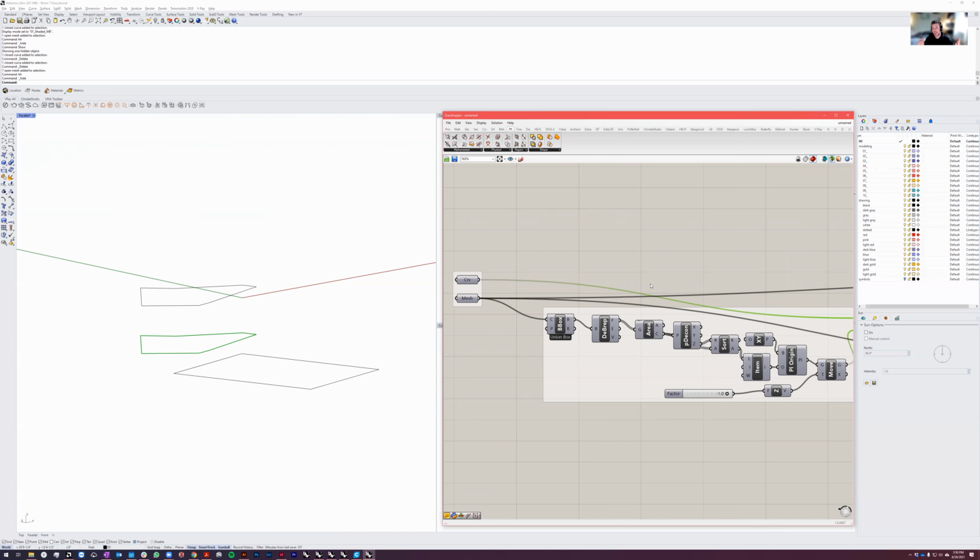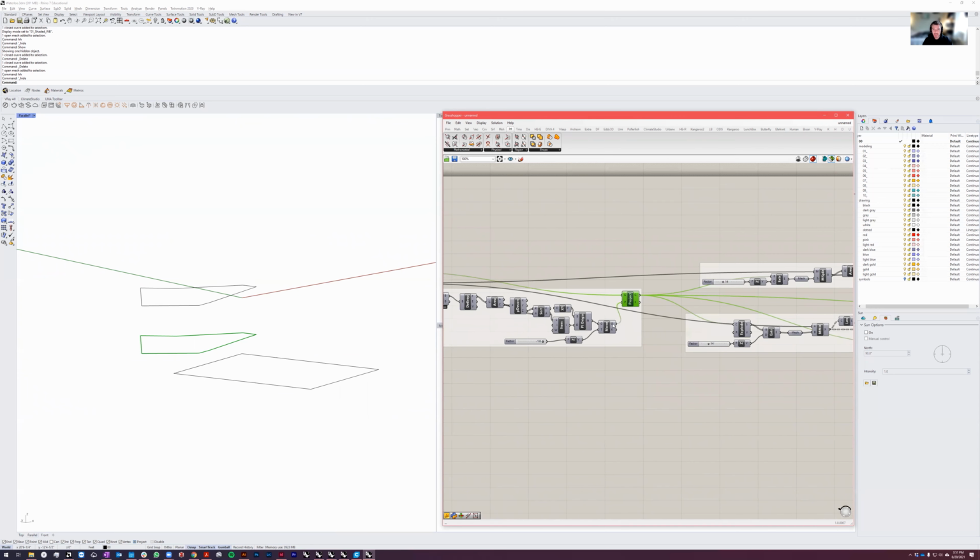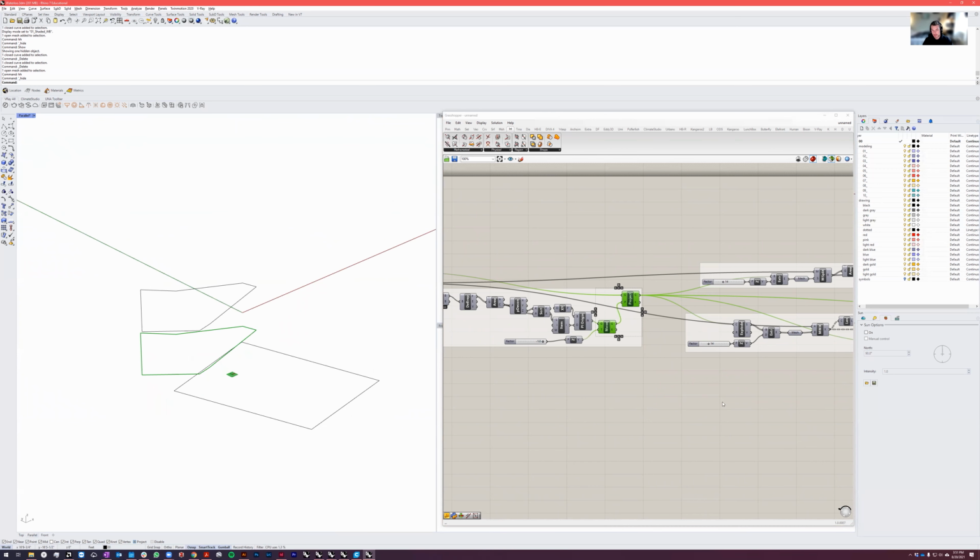It's a little easier to have this built into a Grasshopper script, always projecting and making sure everything's planar how you want it. So you're relying as little as you possibly can on Rhino geometry, which I think in this scenario could be helpful. So I'm projecting that curve down onto the plane that we just created.